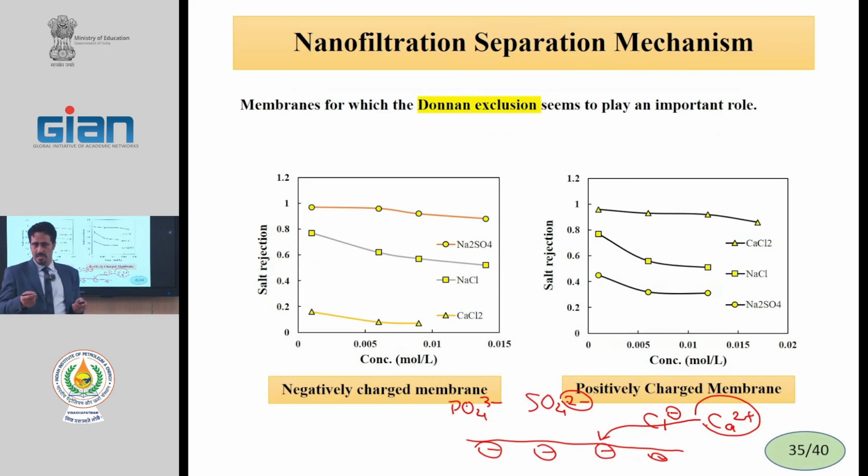Therefore, in the lab, if you have a nanofiltration membrane, with these test results you can find very easily whether the membrane has a negative or positive charge. For measurement of the membrane surface charge, we usually use a zeta potential device, but this simple example can show whether our membrane is positive or negative.